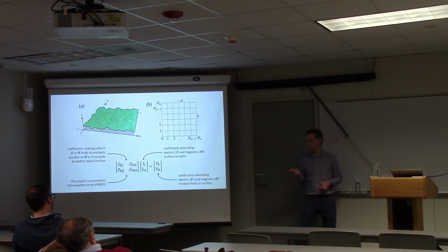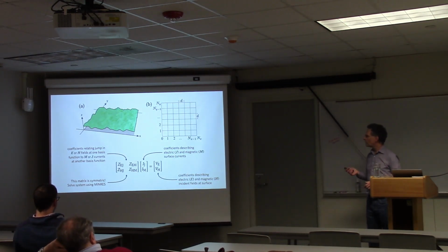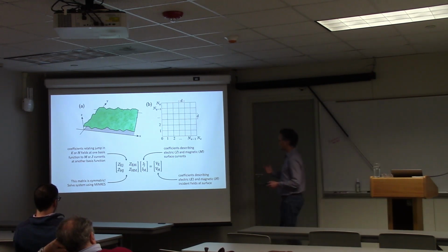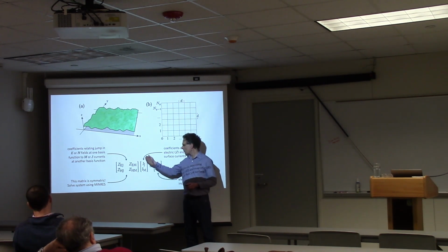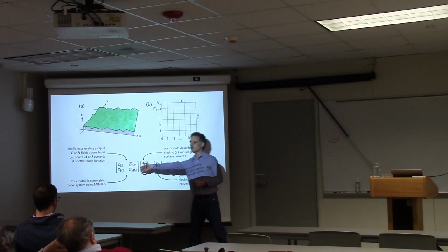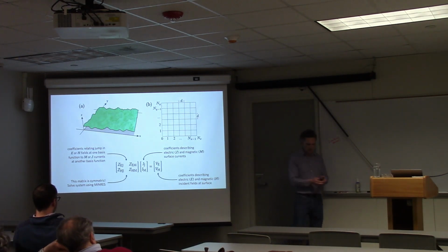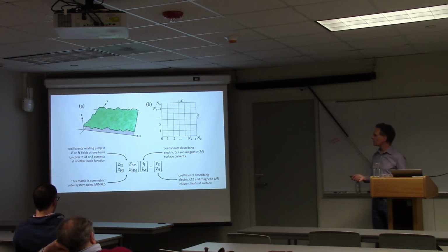We adopted MINRES as the solver for this. So this is an iterative matrix solver, meaning that it's going to do a computation where the bottleneck is going to be taking sort of trial values of this vector and multiplying them by that matrix. And that's the thing that is going to take up all the time. So that's the thing I need to think about doing efficiently.